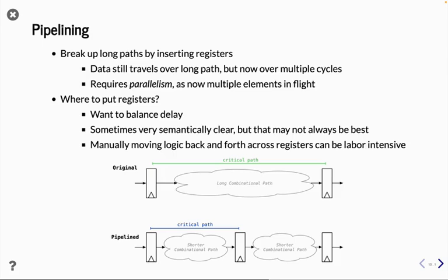This is one of these things where, once again, you want tool assistance, right? Because you can put it one place and then run a tool and see what happens. And remember, when you put it in one place, tools are going to synthesize the logic on both sides. They're going to place and route all the logic. And then you move the register over one gate, and then it actually resynthesizes, replaces, reroutes. So actually it's going to perhaps even be non-monotonic in ways causing changes in delays. It's going to be very labor and time intensive, right? Where you keep tweaking things and watching what happens. And so naturally the question is, well, can we somehow automate this, make tools do the work?